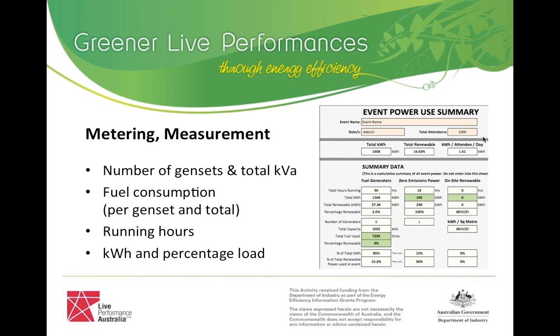And if we return it full of fuel, then you know exactly, by the fueling company, the refueler that's been employed for the event, how many litres have been used. Provided you don't double up on ancillary equipment, as in forklifts or vehicles, of course. You need to isolate your power usage, or pretty much your fuel consumption. You have to look at your scenario and work out how much fuel's getting put into each genset.